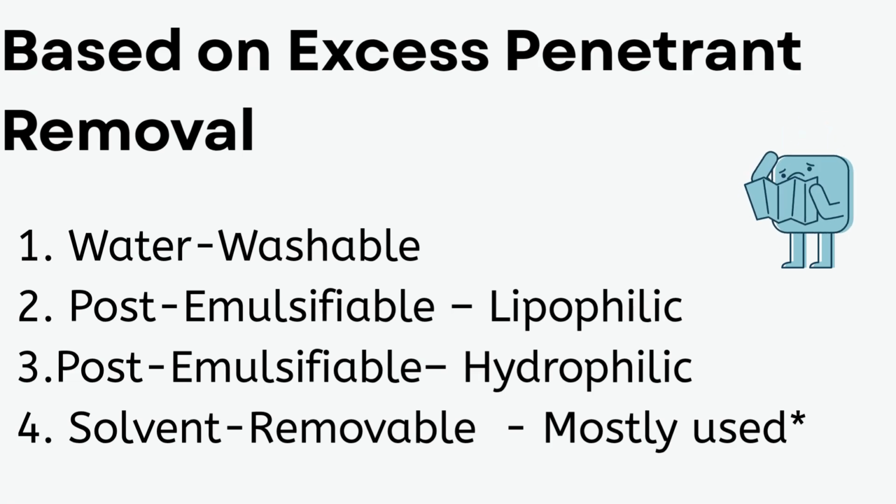4. Solvent removable. Extra penetrant is wiped off using a special solvent and a clean cloth. Often used for small parts or when water can't be used. Portable and simple, good for field inspections.